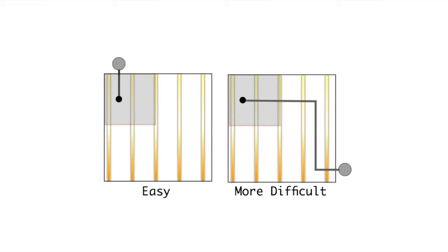Joist and waste positions. It is much easier to have your waste pipe running in the same direction as the joists rather than across them. It is sometimes possible to core through joists to run a waste pipe, but this is governed by building regulations and is limited to no more than 25% of the joist depth.